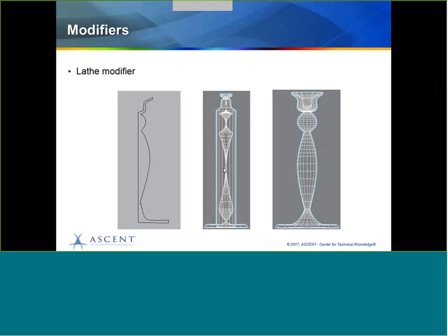Easily, in the parameters, you can correct this by simply pressing the min alignment option, and by simply pressing one option in the parameters of the lathe modify panel, you can get a candle stand, and the center of alignment, the center point, will already be fixed for you.